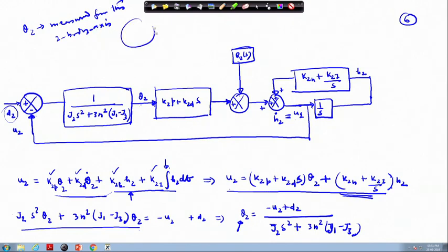If we take the first rotation about the, because your system, this spacecraft is rotating. So, the first rotation you will give about the 2 axis. Okay. So, theta 2 is measured from the 2 axis, and thereafter you will give the 3 and 1, as we have done in the case of the spin stabilization.